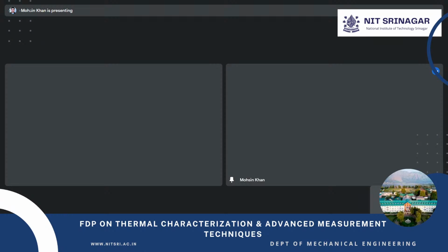So these signals ultimately generate an image. Let me go back to this image. In this black and white image, you can see some dark spots and some light spots. This basically indicates the difference in density, in composition, and in how a material reacts to the electrons. This way we can interpret our SEM image.